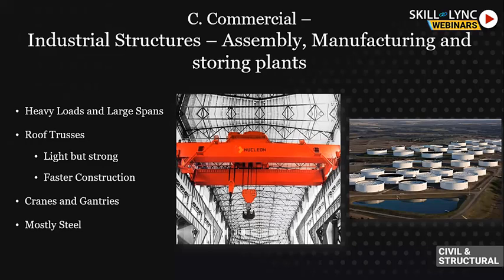Now, one typical challenge that you would see because of these large heights is, let's just say I have a roof of concrete. Concrete gains its full strength in 28 days. If I have to build the concrete slabs, I will have to do the shuttering on the bottom. If I have a huge span, imagine the shutters standing for that height. It's very challenging to provide shutters for that height. That is why typically they go for steel structures, because with steel you will have a crane standing somewhere, assembling all these steel members, and then they get welded or bolted on the top.